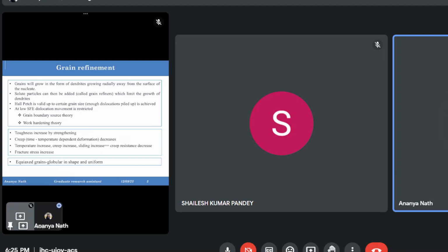The dislocations pile up, and then low angle boundary, high angle boundary, all those things are related to this type of theory. So grain boundary can itself give rise to new grains, and new dislocations, which may in turn give rise to new grains. So that is one thing of grain refinement. There were some formula discussed about it, like how much length the dislocations really need to travel to get those new grains or high angle dislocation pile up.